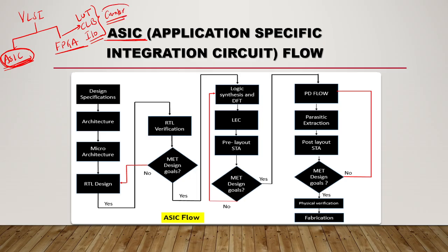You can write the Verilog code, convert it into a bitstream file, and load that bitstream file into the FPGA. The FPGA will work as a counter. After some time you can write an FSM, some sequence detector, and if you load that program, the FPGA will act as a sequence detector.